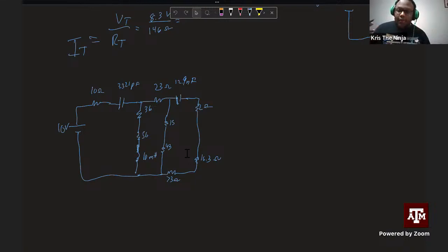So this is 2 lessons in one. This is teaching you to pay attention to what you're doing. This is a DC circuit, you'll notice because of a battery. If you see a battery like this, it's a DC circuit. In DC circuits, I didn't tell y'all this for a reason, because I wanted to teach you this quickly. In DC circuits, capacitors act like an open circuit.